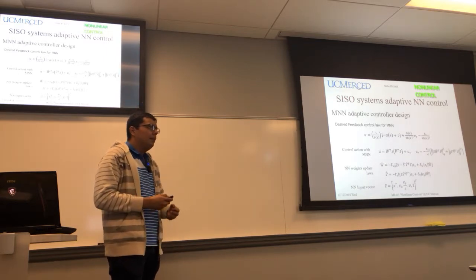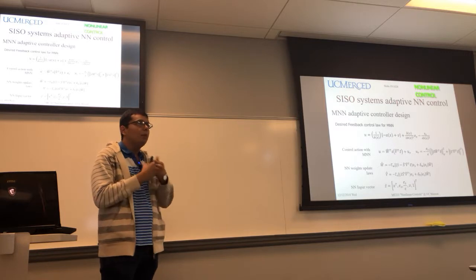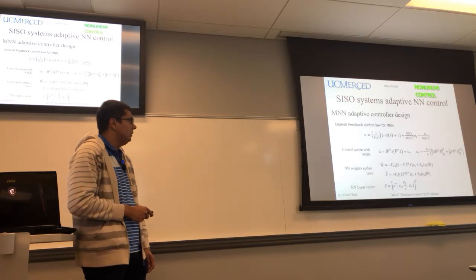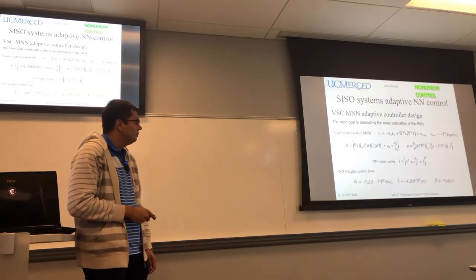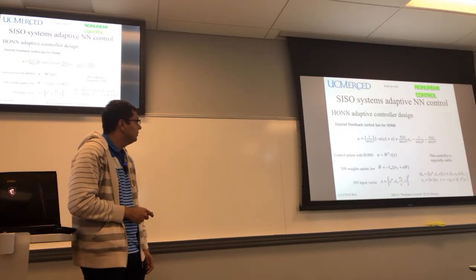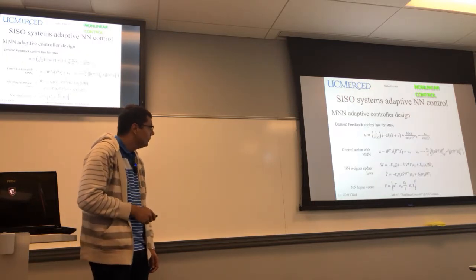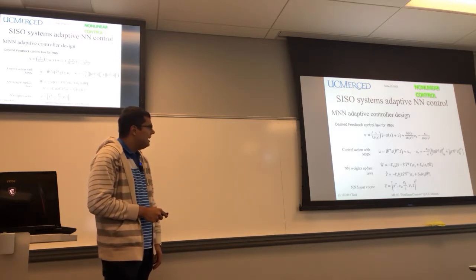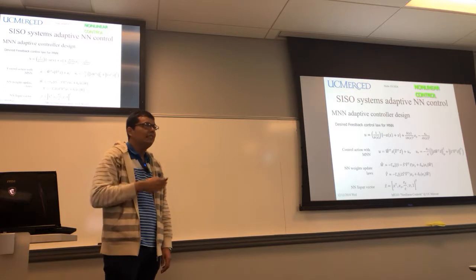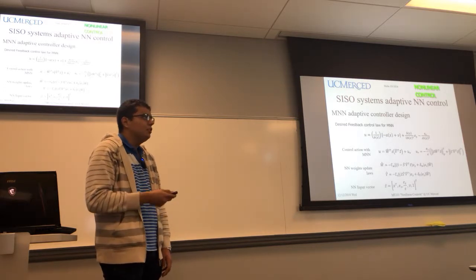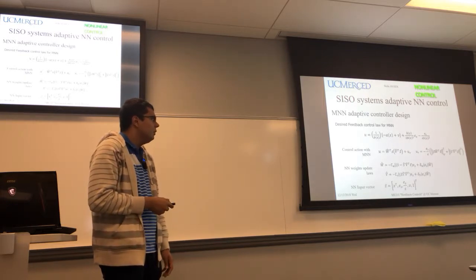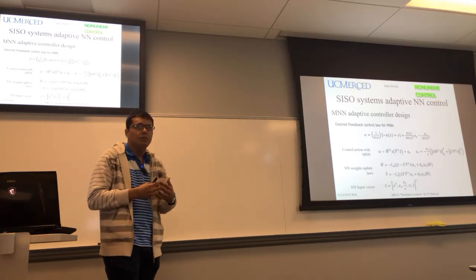In the case of multilayer neural networks, it's also possible to employ this control law. In this case, the control law will estimate all these dynamics. If you see, it's pretty similar to that law. In this case, our control law has the multilayer neural network that estimates this desired behavior, and we have this UR term. This UR term basically is the noise, the estimation noise of our neural network. With this equation, we can estimate the noise of the system in order to improve the robustness.